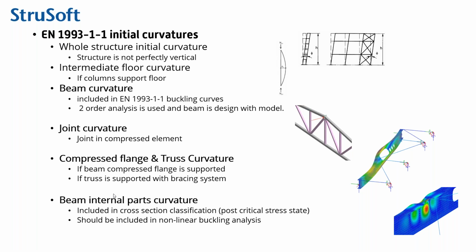What is the spring stiffness you are using for foundations, and how to calculate it if it's, for example, 100 millimeters of gravel? Okay, this is a difficult one, and usually it's missing from the calculation models. But we can ask the geotechnical engineer. That is the first option. Then, if we don't have that answer, we can do some bedding modulus analysis based on the soil type. There are different types of soils, and they give you different kinds of stiffness.